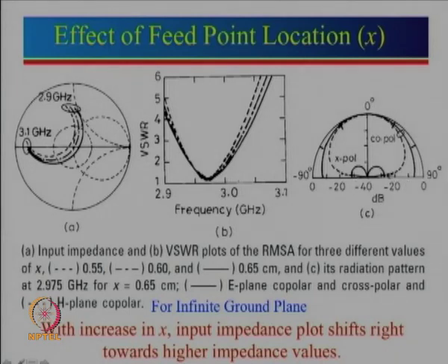So, what is this component coming here? This is actually a cross polar component. Ideally, we would like there should be no cross polar component. A perfect linear polarized antenna should not have any cross polarization, but however, as one can see, the cross polar component is, this is 0, minus 10, minus 20, minus 30, that is about 27, 28 dB down compared to the maximum radiation in this direction. So, we can almost say cross polar is very less, but however, from where this cross polar is coming?